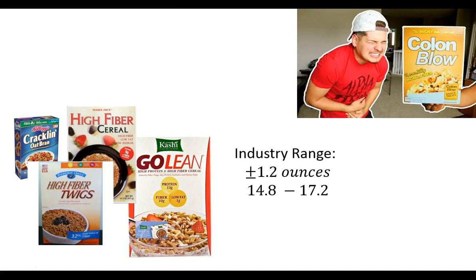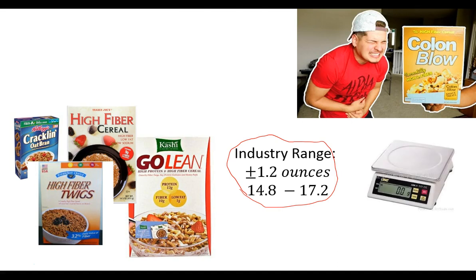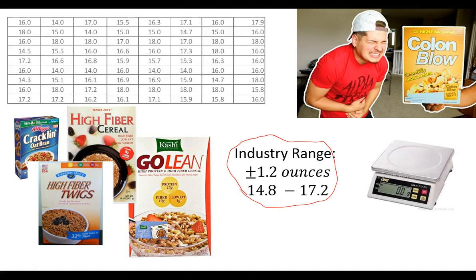What they found when they looked at several samples of this product weight was that they were ranging just 1.2 ounces away from their average, or a range of 14.8 to 17.2 ounces. So it's a bit narrower range than our 14 to 18. This is going to become very important. This is what the customer finds acceptable, and we found it simply by looking at our competition. That's what the customer is expecting, and we're not doing that. We're going way wider than that range, and again, we actually measured that on the scale and came up with it.